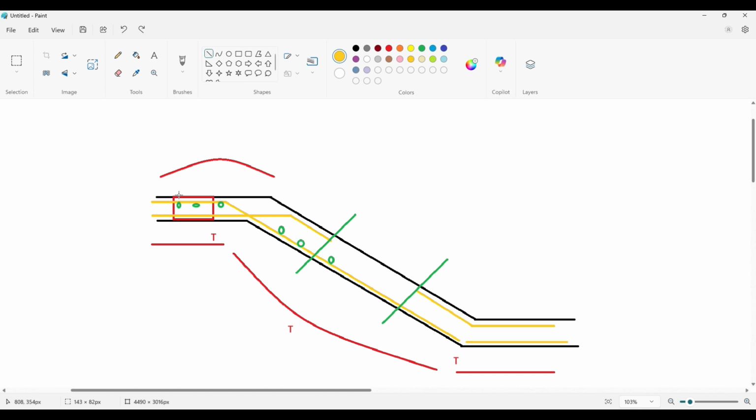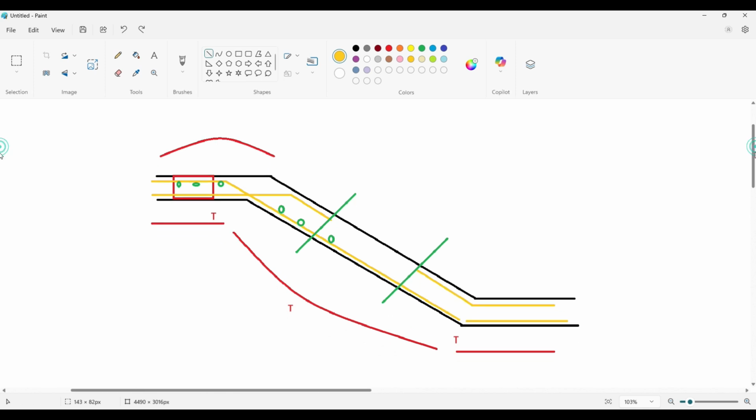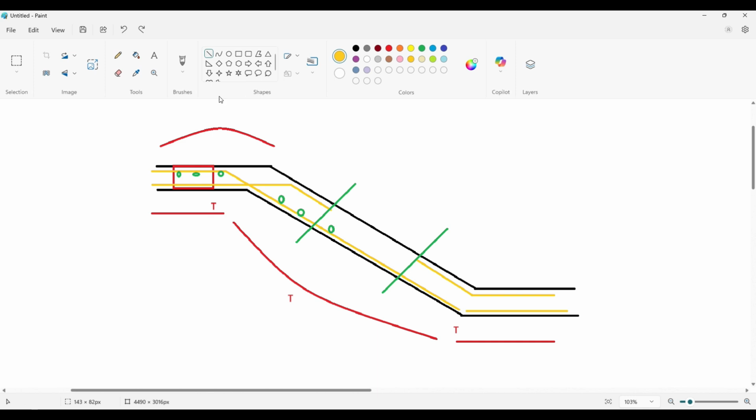So the bottom bar will come and become the top bar, and the bottom bar will come here and become the top bar over here. All right, if there is a requirement, we provide an additional amount of reinforcement. And if we have a plinth beam, basically all these bars will come over here. For example, if this is going to be my plinth beam, you can just make it brown or something. Let me just keep it black. Okay, so if there is no landing as such and there is a plinth beam, the bars will just come and terminate over here directly. Whatever bars are there, they just terminate over here like this.